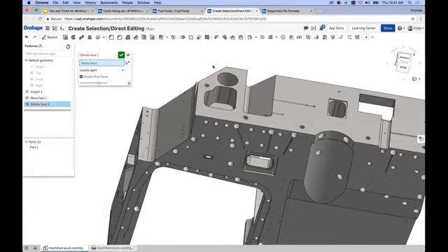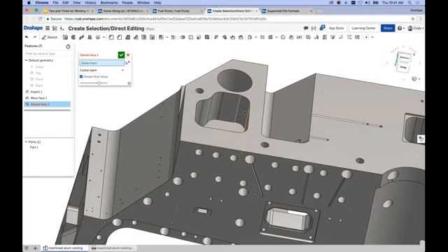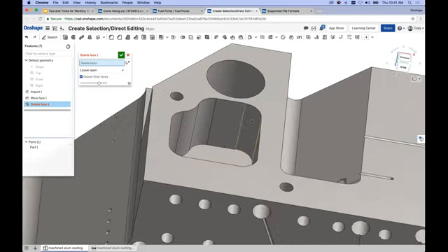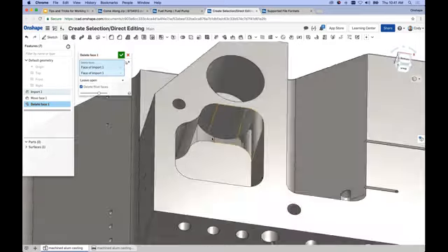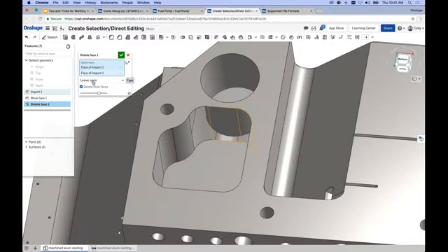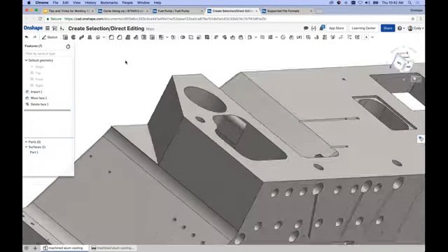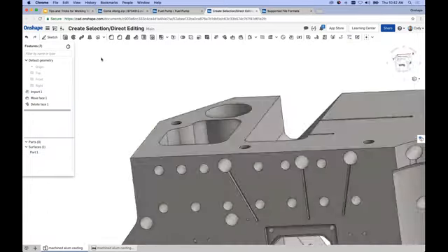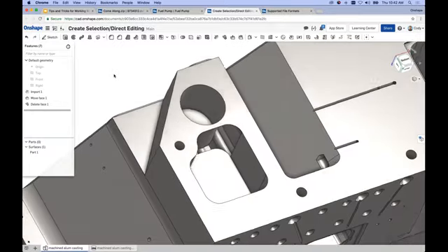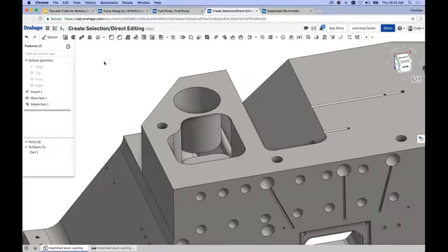All right, so I've imported this geometry, and for whatever reason, I need to remove a few faces and recreate them. Maybe they're bad geometry, or they have some kind of an issue. I can go in and select the faces, and with the leave open option on, it then converts immediately to a surface. So you'll see I no longer have a solid part, I have a surface. Right, so we've gone from solid to surface via the delete face. I hit the green check OK, and now we have a hollow, quote unquote, model.